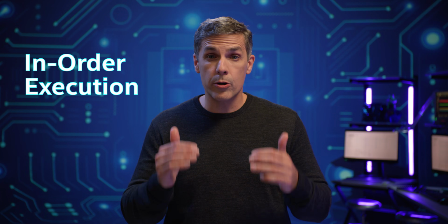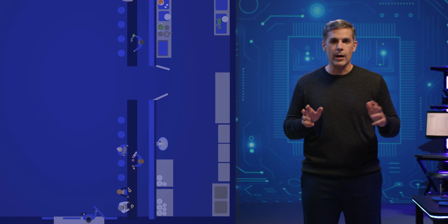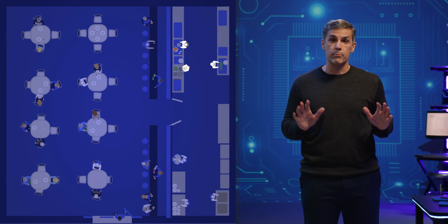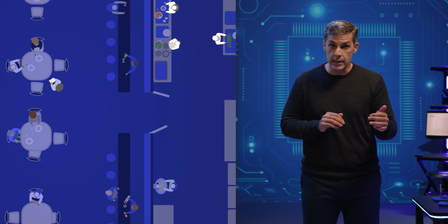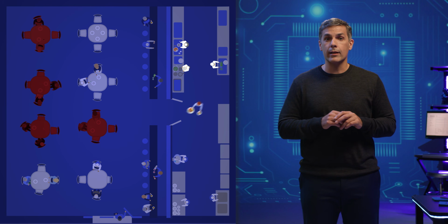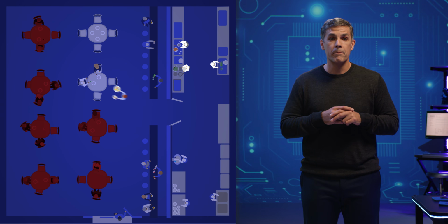In a basic microarchitecture, the UOPs are executed in program order, which is called in-order execution. However, in order to provide the best performance and energy efficiency, executing them out of order is actually better, allowing code to execute faster as we remove unnecessary wait times. Imagine you're running a restaurant. You have tables full of customers, and you have many cooks in the kitchen, and you want all your customers to be happy. You could let the first table seated order and eat first, and then move to the second table, but you would likely go out of business quickly as everyone watched the first table eat.